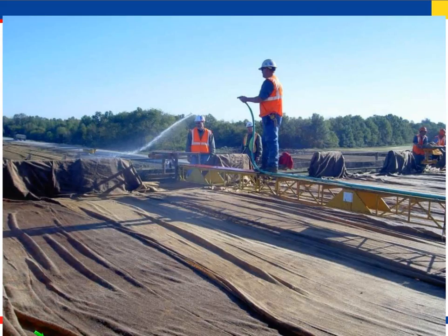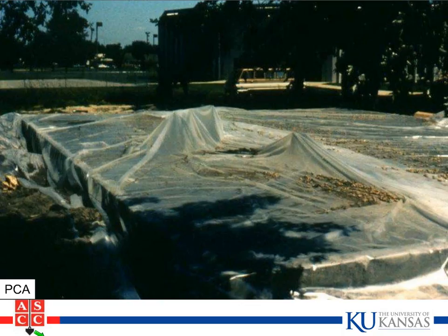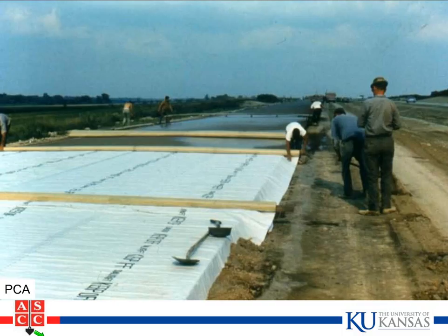Next thing is you keep the concrete wet. You just don't let it dry out until you're ready to let it dry out. So they're keeping it wet until the concrete is fully set, and then typically, if you want to get it right, you put soaker hoses and you put the plastic on it. Now, other methods of curing. Here's another example: putting a sprinkler on burlap. Putting plastic on the concrete. Of course, this is going to affect the appearance of the concrete to some extent if the plastic comes in contact.